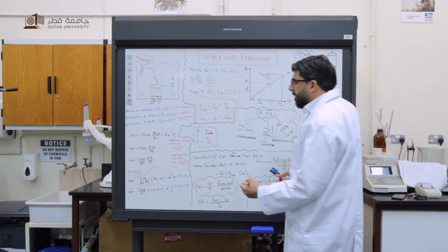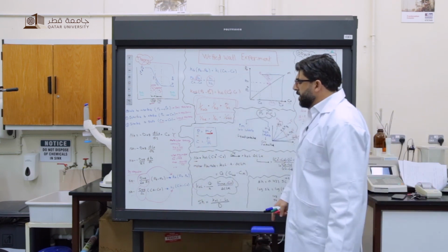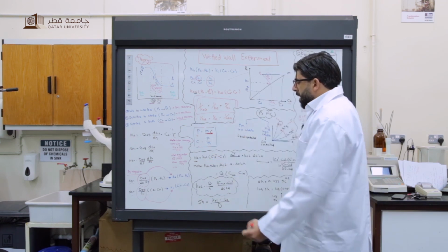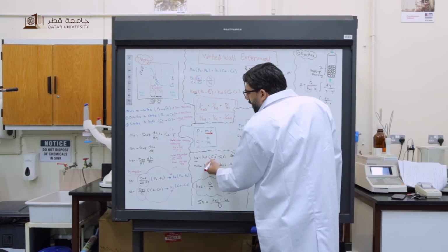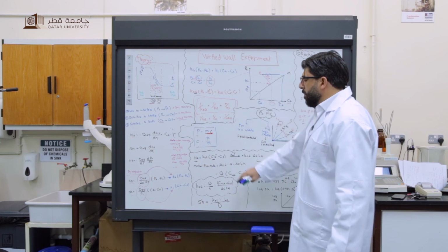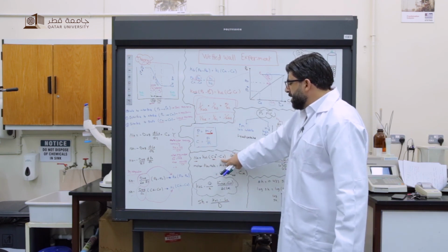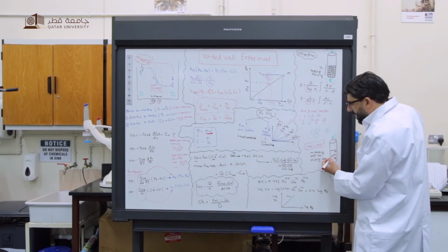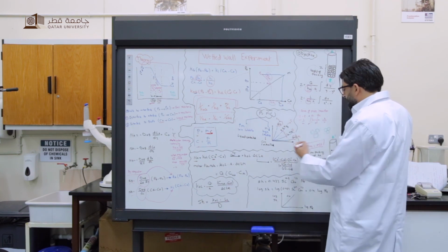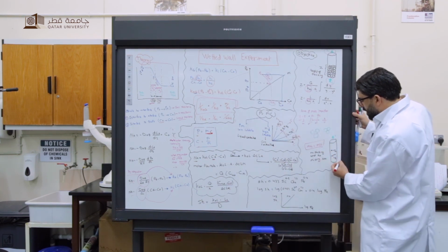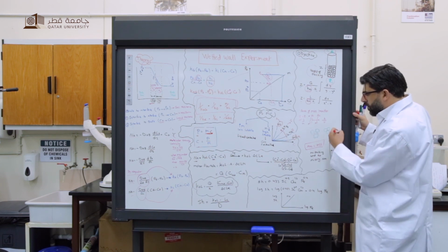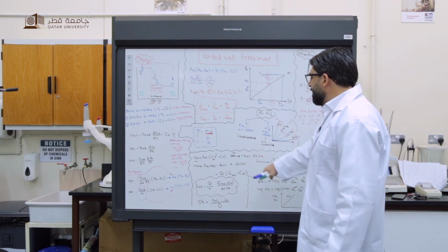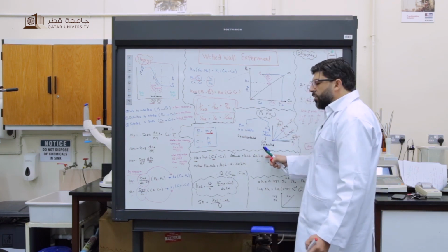So now we know that the flux of oxygen is equal to the overall liquid mass transfer coefficient KOL times the saturation or equilibrium molar concentration of oxygen, C star A, minus CA. Because this is for each point, by integration from CA1 to CA2 through the column, the flux equals overall KOL times delta CLM, the logarithmic mean.